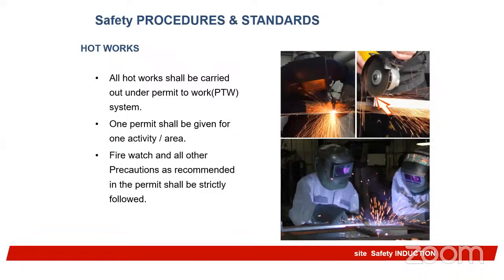Hot work, there's a permit for hot work. Hot work, welding operation, and that has to do with grinding, heating, and lights. There should be a permit. One permit shall be for a particular area, depending on what is obtainable in your own workplace. Maybe a particular location has its own permit. A permit can be for 1 week. You must have a fire watch. You must have a fire extinguisher that has been checked. Your equipment must be checked properly. There must be a supervisor there at all times.